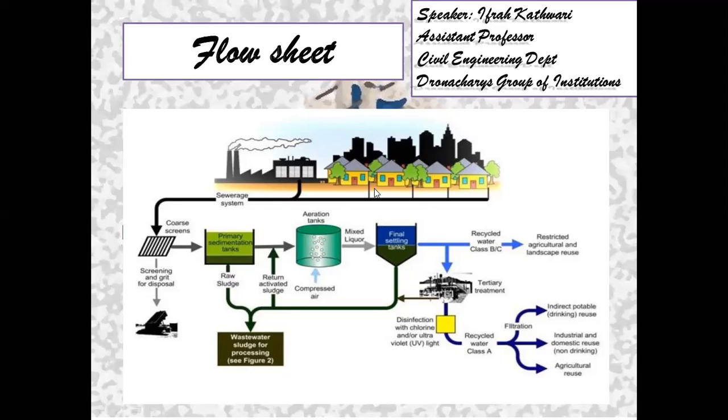Okay, so the water is coming from commercial buildings, from residential buildings, and from factories. As you can see here are the underground pipes that are laid for the supply of this wastewater towards the wastewater treatment plant. This is known as a sewerage system, and the water is flowing through it under the action of gravity. Herein we have a lifting station, wherein there is a pump which lifts the water towards the treatment plant.